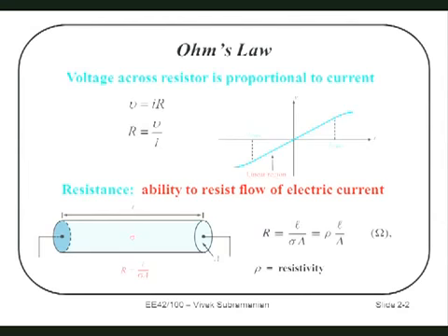It's a quantum mechanical process called tunneling, which we're not going to talk about in this class. Turns out, by the way, at low voltages, you'll have to get them within about 2 to 3 nanometers of each other. But we do that. It turns out in your modern microprocessors, the wire on the top of the transistor and the bottom of the transistor are close enough that some fraction of electrons actually jump.